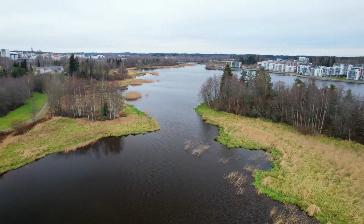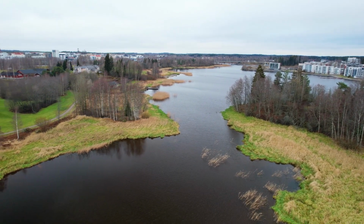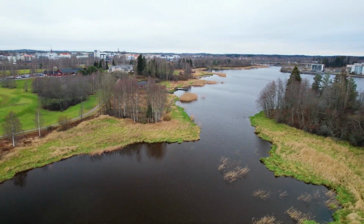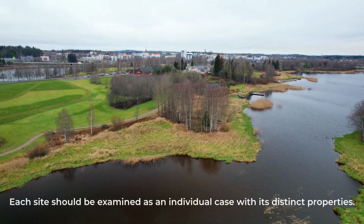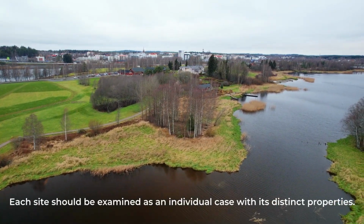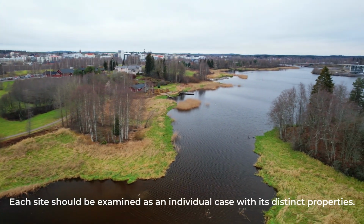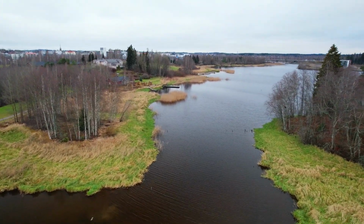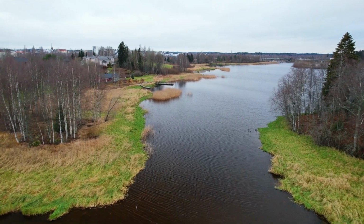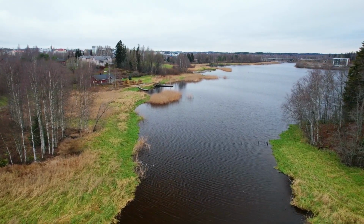The key to water monitoring is a good knowledge of the region and taking the aims into consideration. It is important to look at each sampling site as an individual case with its distinct properties. When investigating areas, you also need to look beyond the water, into the catchment area. The reason for a deterioration in water quality can often be found in the catchment area.